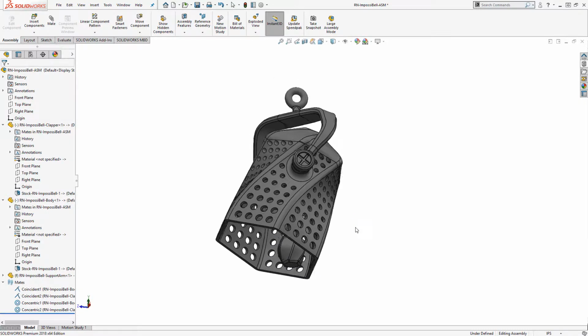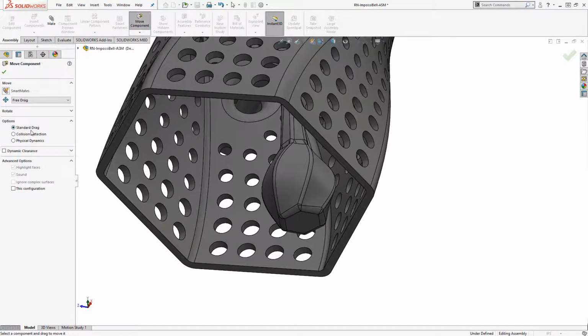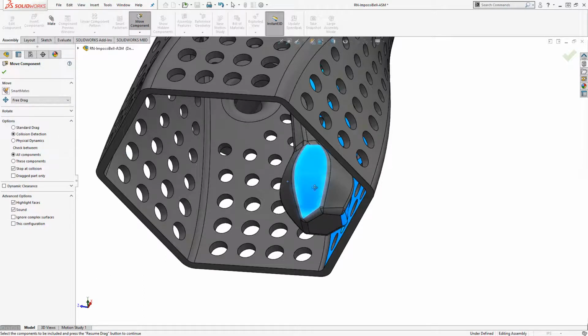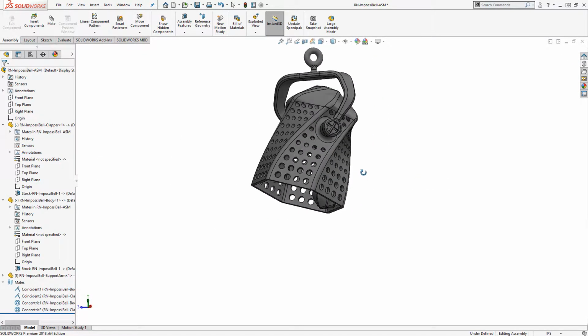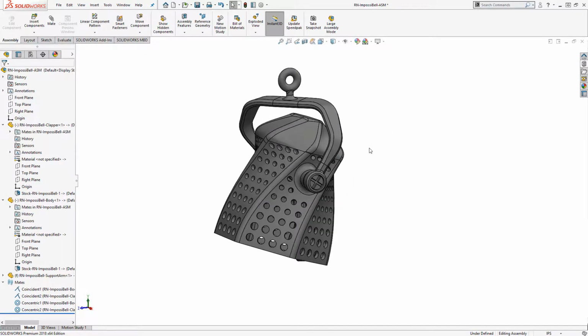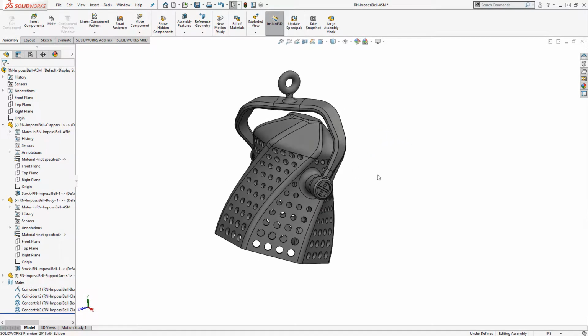We had about 0.5 millimeter clearance between any wall, which was just a number I chose. I thought it was a reasonable value for the printer. I hadn't actually printed an as printed mechanism before on our HP, and I was really happy with the result. I don't think of anything I could improve on this one, and I'm happy to be able to do challenges like this at Hawkridge. It's a fun thing.